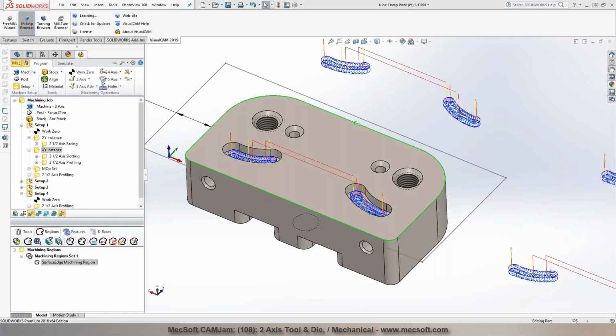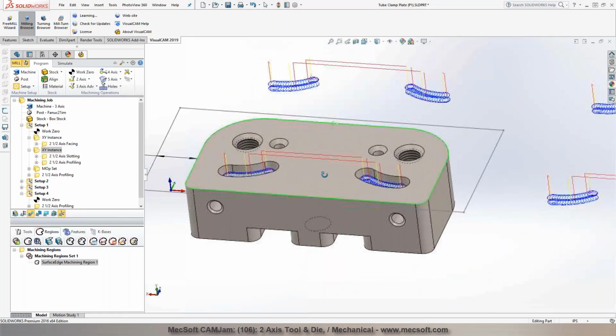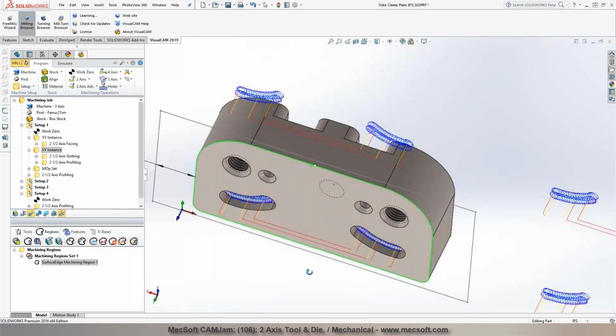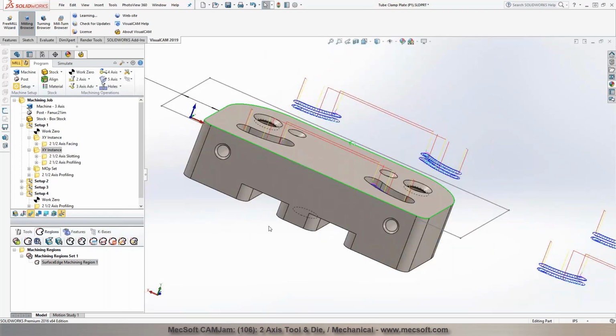Would you be looking to do a continuous rotation, or would you be looking for more of an indexed approach, where you rotate it and lock it into a specific orientation to program? So, for example, if you consider this part to be set up on a 4th axis, you could do 0, maybe 90, 180. Would that be how you would program it, indexing it, or would you want to be able to do continuous 4-axis machining? No, for the immediate need it would just be indexing.